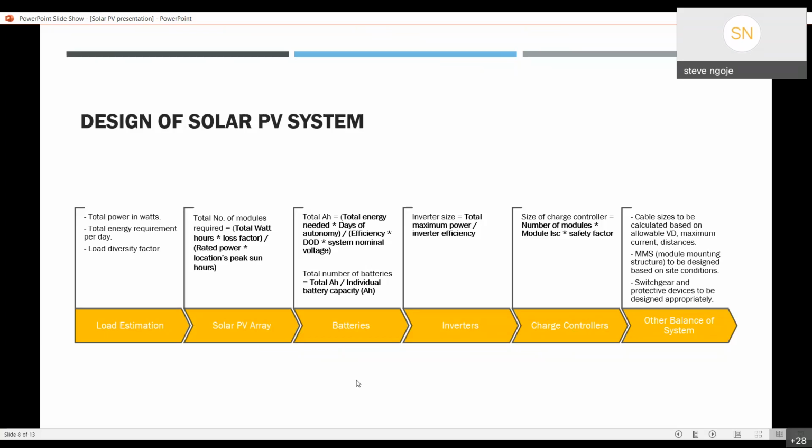You go there with power loggers and connect them for whichever time frame will work best for you, a week, 2 weeks. Try to have this done during a period when they are operating at their maximum, at their peak. Based on that, you'll analyze the consumption and you will size the system.